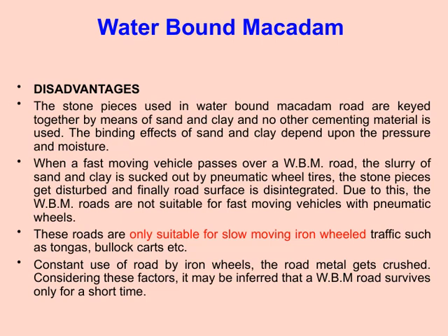Now, let's discuss the disadvantages of water-bound macadam, or WBM roads. One of the main issues is that the stone pieces are only held together by sand and clay, with no cementing material added. This means that the binding relies heavily on pressure and moisture conditions. If either of these changes, the stability of the road can be compromised.